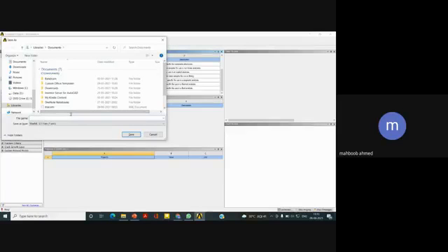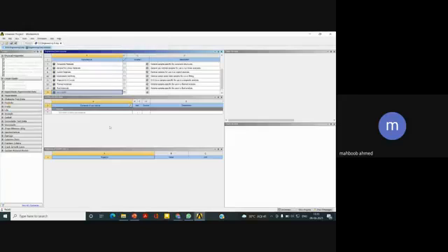It will ask where you want to save the data. So you just name it new material. I'm just taking these names arbitrarily. Just save it. Now you have created the new material library, and now you have to create some materials also. I am naming this my fictitious material one.